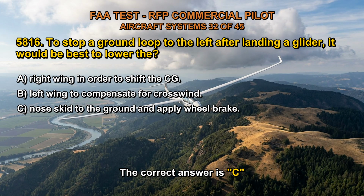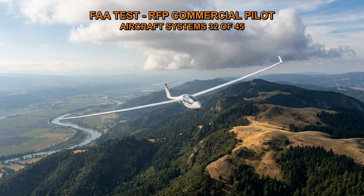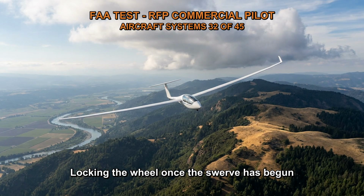The correct answer is C. When the glider begins to swerve, the nose skid is useful until it may dig in and cause the glider to twist into a ground loop. Locking the wheel once the swerve has begun will help. Apply heavy pressure on the brakes.